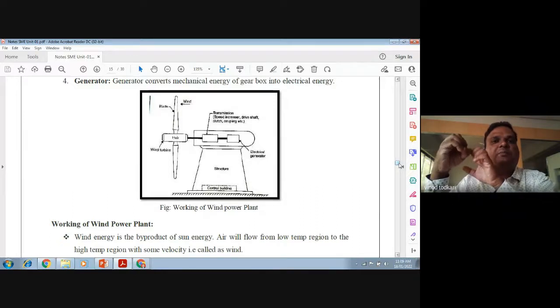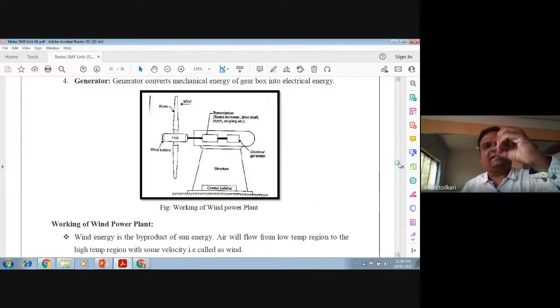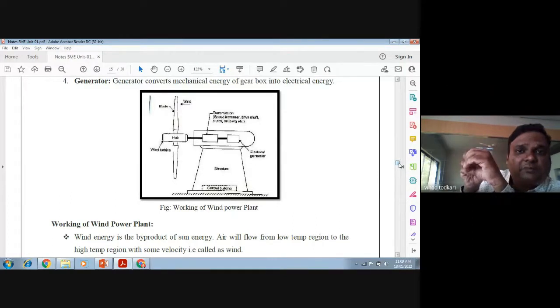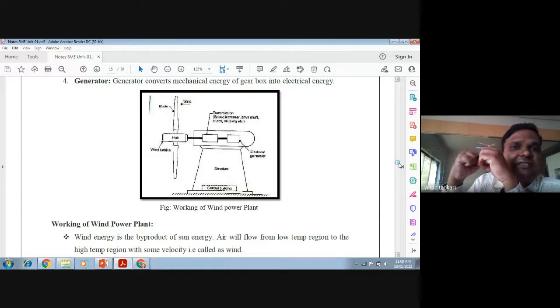This will also perform 60 revolutions in a minute. Now let's say that this is your driving gear, its diameter is quite high, and this is your driven gear. Its diameter is half as that of the driving gear. Now tell me, if this performs 60 rpm, right? What will be the rpm of this driven gear?